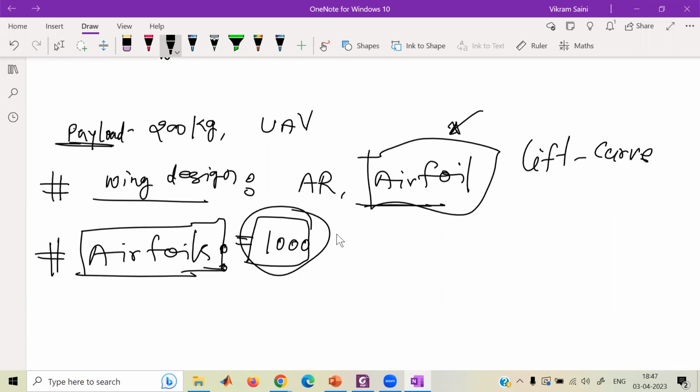Like, sir, the CM alpha curve for the airfoil, the CD curve, and CL versus alpha, very important. It will tell you the maximum angle at which you can climb before the aircraft can stall, and where CL max occurs. What are the desired values for these quantities that you just mentioned? For all of these quantities, we need very high CL at low alphas and a very high stalling angle.